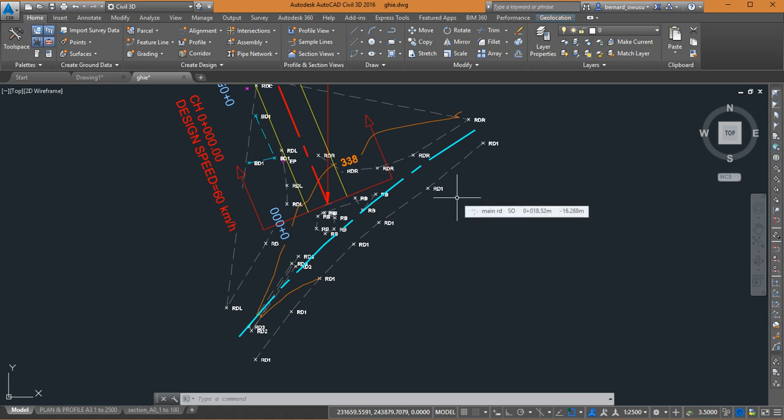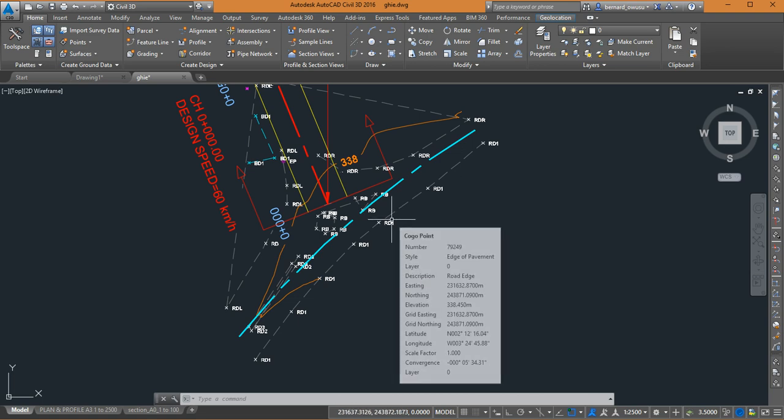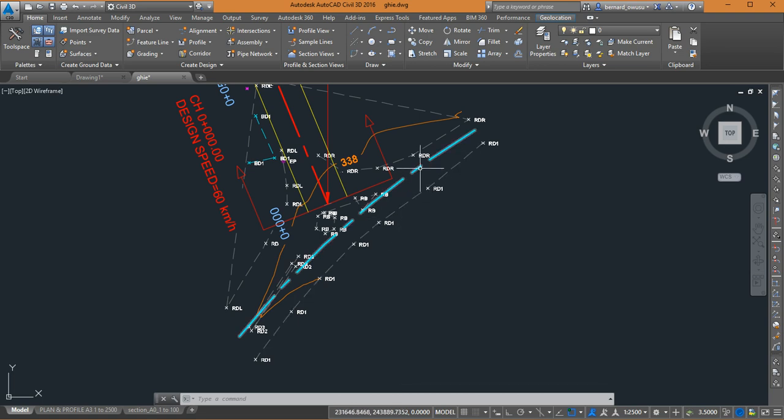Please, are we okay? Successful. Have you been able to draw the alignment? Okay, if you are successful, before you can have an intersection, you need a plan, an alignment and a profile, because it is intersecting both in plan and in profile.